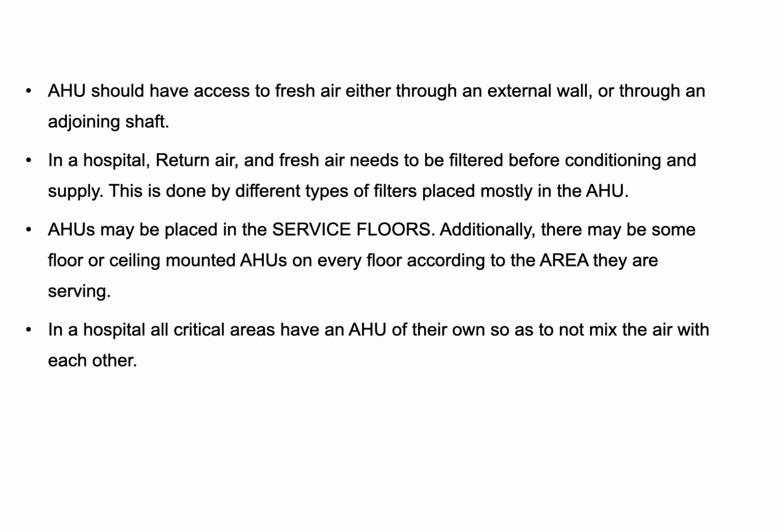In a hospital, return air and fresh air needs to be filtered before conditioning and before supply. This is done by different types of filters placed mostly in the AHUs. AHUs may be placed on the service floors. Additionally, there may be some floors or ceiling mounted AHUs on every floor according to the area they are serving. In a hospital, all critical areas have an AHU of their own, so as not to mix the air with other areas.